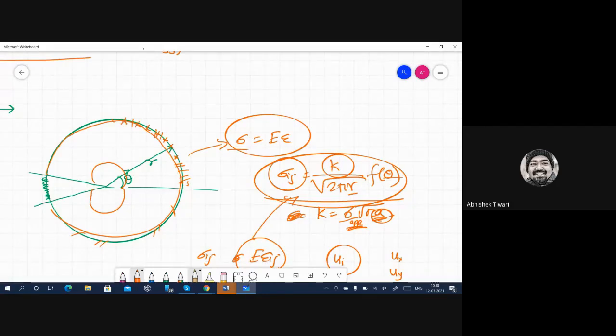And if I can ensure that by applying a boundary condition in my model, then I ensure this equation is being followed in this scoop of material. And then I'm sure that T stress is 0. I'm in the plane strain condition with a small scale modeling and small scale yielding condition, and the rest of the things we can go further from here.